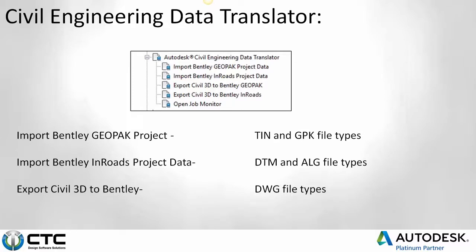Geopack, if you're not familiar with MicroStation, what that would import is a TIN or a GPK file type. The Inroads project would import a DTM or an ALG file type. And then obviously going Civil 3D to Bentley, we are looking for a DWG file type.